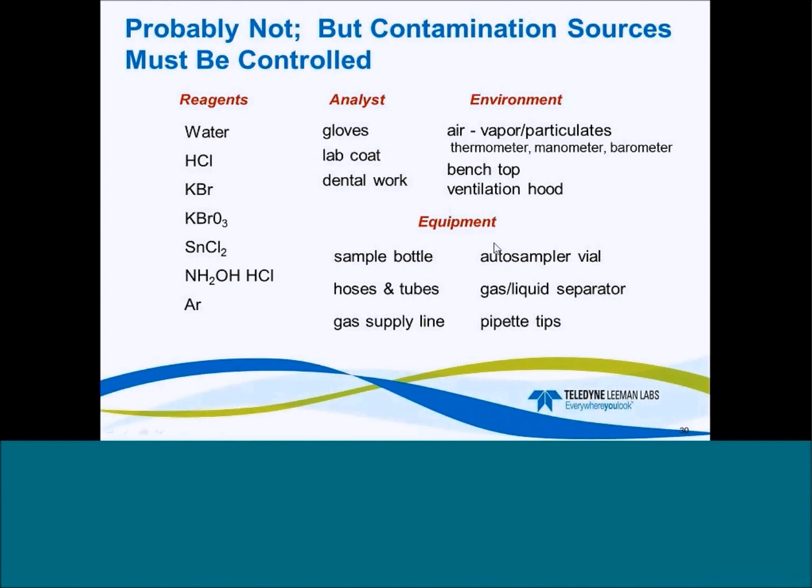And of course, the equipment itself. As I mentioned earlier, the sample collection only allows fluoropolymer containers and borosilicate glass. The equipment that touches the sample needs to be certified to be clean. That actually is part of the procedure, part of the method. But the contamination can come from sample bottles.